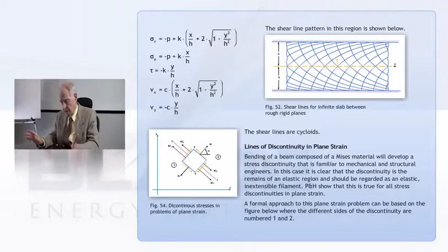And consequently, in the case of this beam, you can look at that layer that's halfway through it as what Prager calls an inextensible filament. And along that, you can bend it any way you want. It's got a general solution that just says that the displacement is just any old function of the coordinate along the filament.